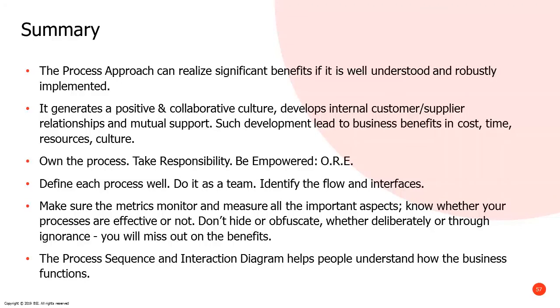So when we did the PFMEAs as part of introducing PPAP, I was the facilitator. When we wrote the processes, I was the facilitator. I asked them, what happens next? How does that happen? What is the risk? What could go wrong? Through doing that, we got the engagement of those guys in owning the procedures, in owning the outcomes of their sections, their teams. And we even got benefits in the PFMEA because they came up with the real problems, which they hadn't recognized as being problems.